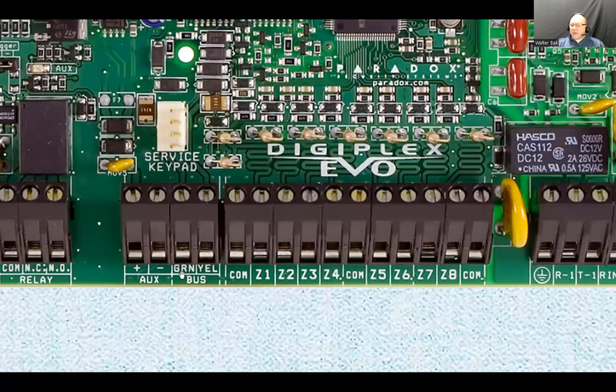Now you see this one shows green and yellow. That's because the cables used for alarm systems are typically called Z type cables. For the most part, it's a quad, which has 4 conductors, and it's using the old color code for POTS, which would be green, red, black, and yellow. Right?